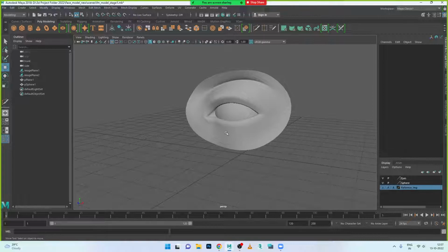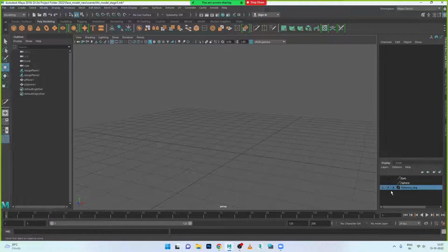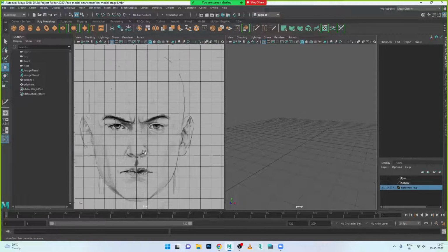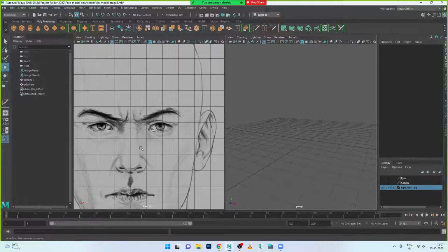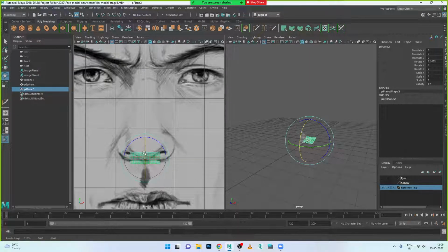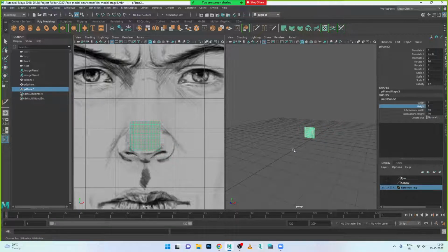Now coming back to the next portion. After this one, I need to hide everything now. I don't want to hide this reference image. Why? Because the other portion, means other direction, we don't have this one now. This portion is completed. Let's come back to the nose area now. Okay, so zoom on this area. Now go and take the plane tool, rotation tool to rotate and make it 90 degrees rotation. Move tool and try to move up in this one now. This is the main base, and we can increase the size for this one. Height we need to increase.